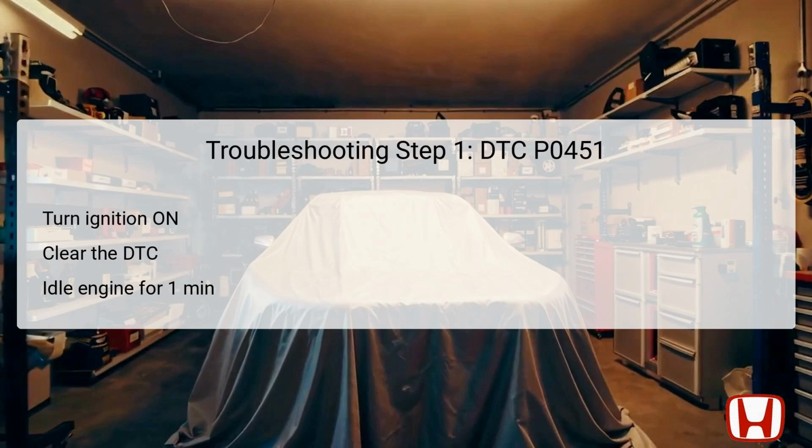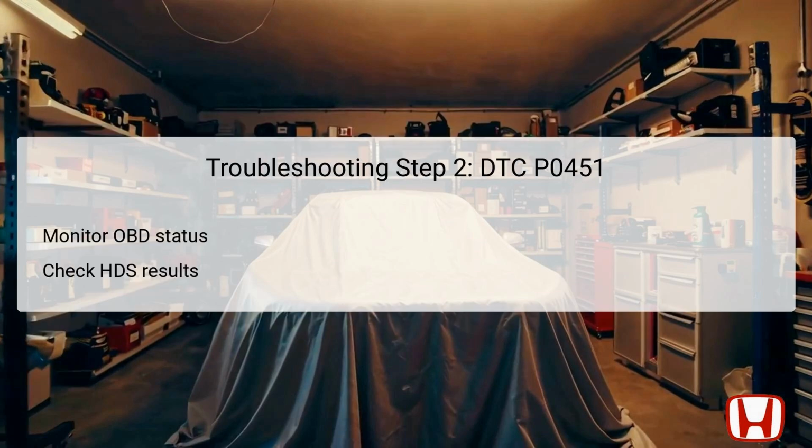Next, start the engine and allow it to idle for 1 minute. This idling period is crucial, as it enables the system to stabilize and collect relevant data regarding the FTP sensor operation. Observing any changes or discrepancies during this initial check helps in effectively assessing the vehicle's current condition regarding DTC P0451.